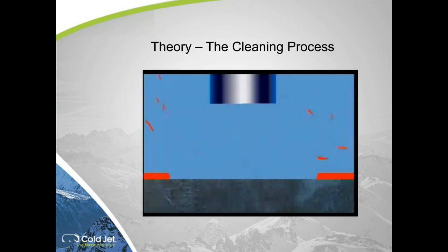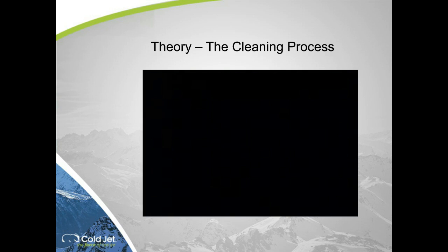If you can understand those three aspects of it, you can then begin to adapt. How much kinetic energy do I bring to the substrate I'm cleaning now? You're running a hot runner mold, you're cleaning the cavities, you can go at it with a lot of kinetic energy. You get to the top of the hot runner system junction box, terminal strips, wires, you're going to want to lower the kinetic energy so you don't strip the insulation off of the wires.